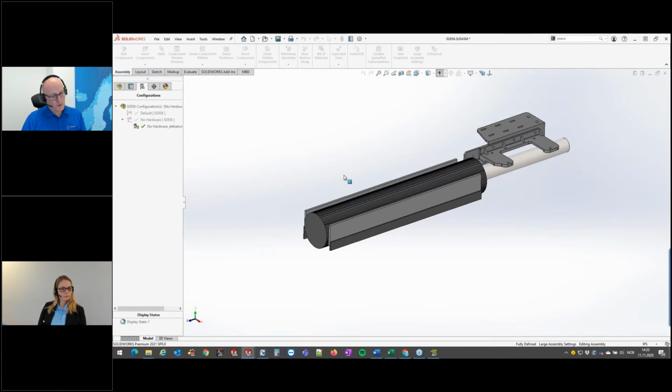And if I want to create a simplified top-level assembly, I can let this defeatured configuration be the visible configuration in the assembly. And as you probably know, on the top-level assembly, you can nest configurations. So from the top-level assembly, you can decide what sub-assembly configuration you want visible in the top level. So by one click in the top-level assembly, you can make a simplified version of a large top-level assembly, which is a very nice new addition to SOLIDWORKS 2021.